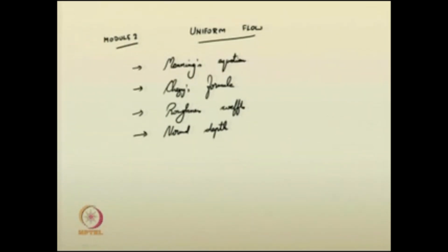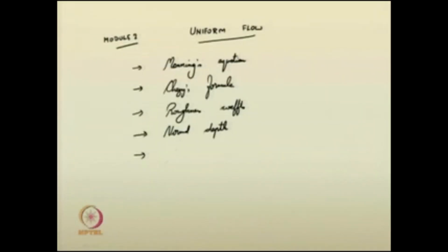So, that quantity was also suggested, and normal depth we have to use it subsequently in many other portions also. Velocity of uniform flow, then most economical sections was also covered. In the non-erodible channels, how you compute uniform flow, that was also briefly mentioned.